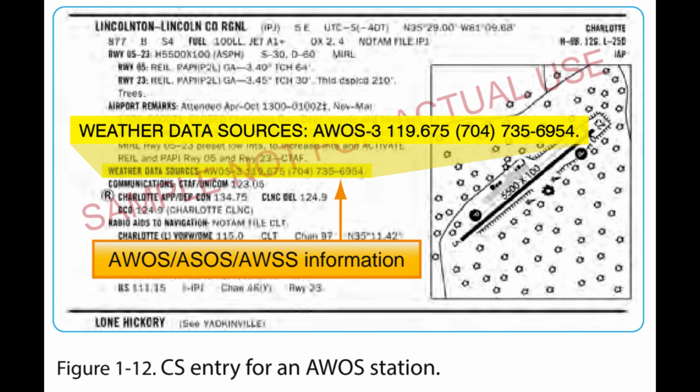While every operator's specifications are individually tailored, most operators are required to use ATIS, RVR reports, and selected reports from automated weather stations. All reports coming from an AWOS-3 station are usable for Part 121 and Part 135 operators. Each type of automated station has different levels of approval as outlined in individual OPSPECS. Ceiling and visibility reports given by the tower with the departure information are always considered official weather, and RVR reports are typically the controlling visibility reference.